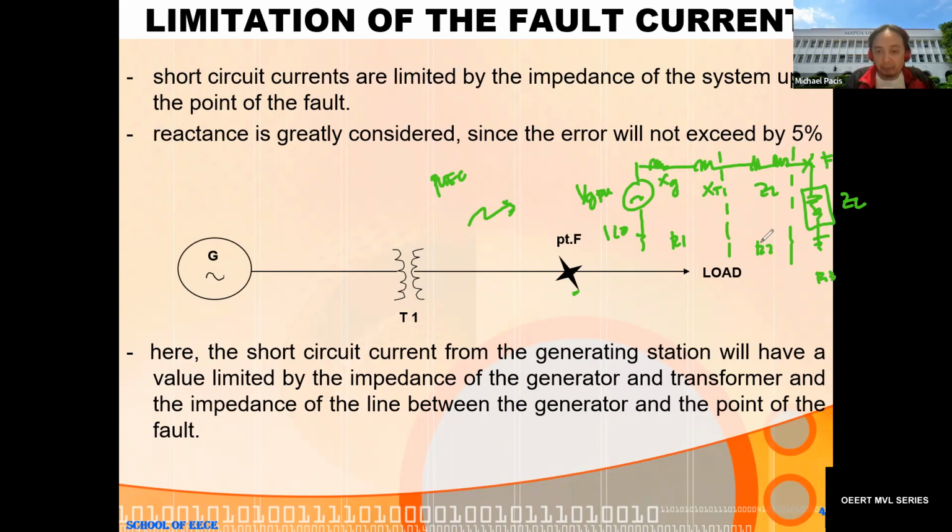Now, the importance of having the modeling parameters here is that you need to know these reactances. That's why it's very clear that you need to have the percentage reactances. So please take note, for example, this is also XG per unit. The only difference between the two is you multiply or divide by 100; it will become a decimal or a percentage.